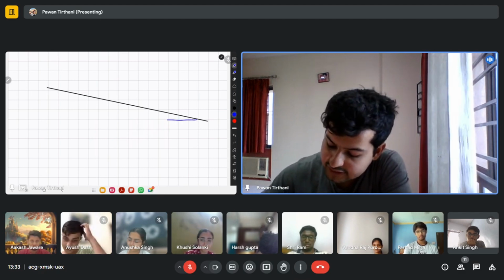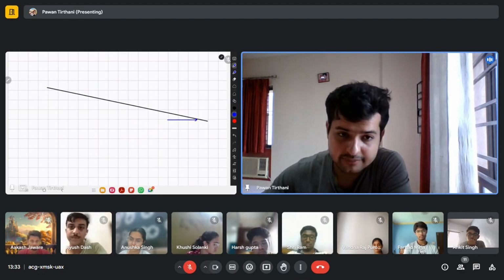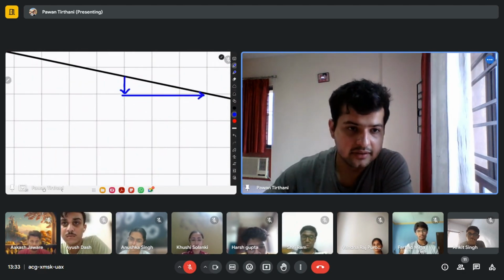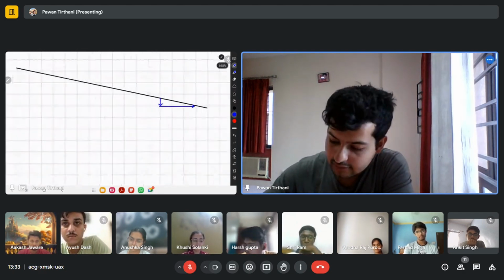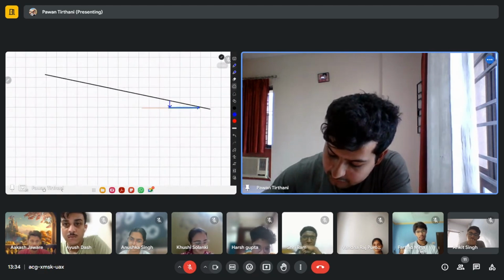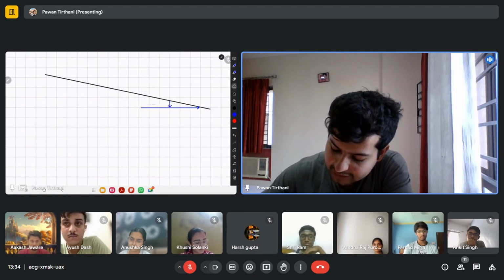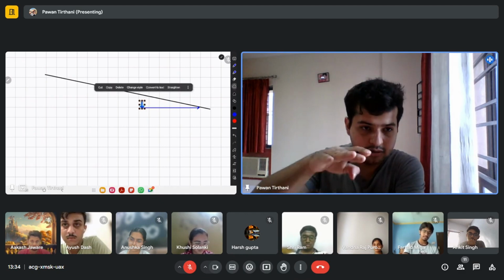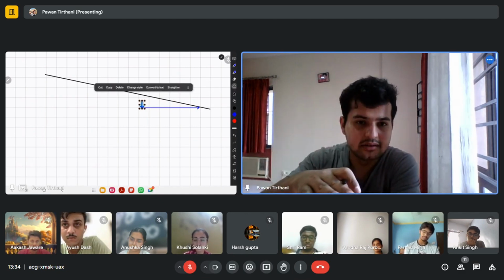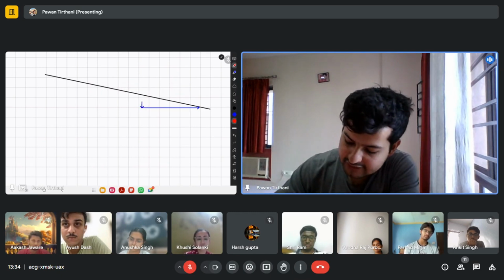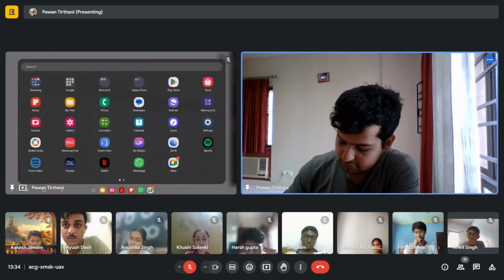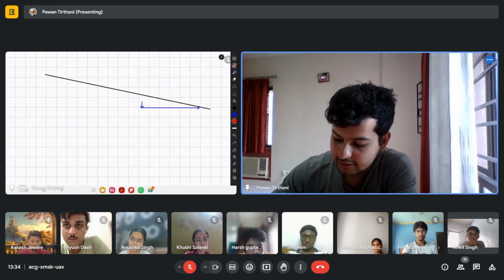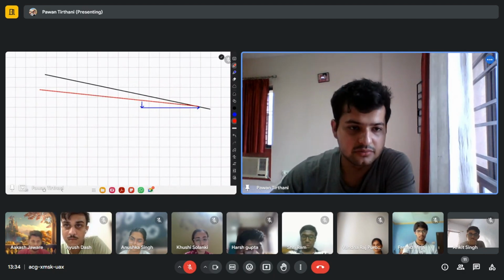मियाँ, अगर तुम्हारी ग्राउंड स्पीड इतनी है, वेक्टर बना रहा हूं मैं, तो तुम्हारा रेट ऑफ डिसेंट इतना होना चाहिए. If your ground speed is less, your rate of descent should be less. But if your ground speed is more and if you keep the same rate of descent, मतलब आप आगे ज्यादा जा रहे हो, you are going ahead more and you are coming down less. So tell me something, will you be able to fly a 3-degree glide slope like this? No, you will be flying a shallower glide slope.